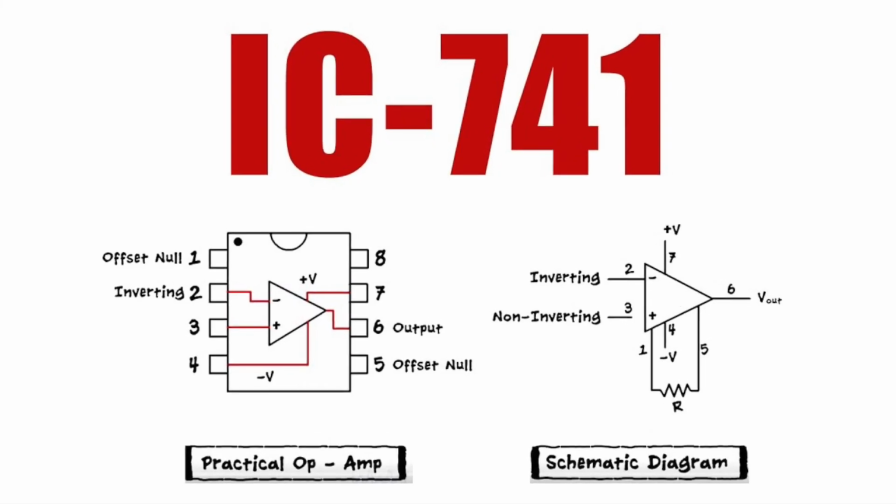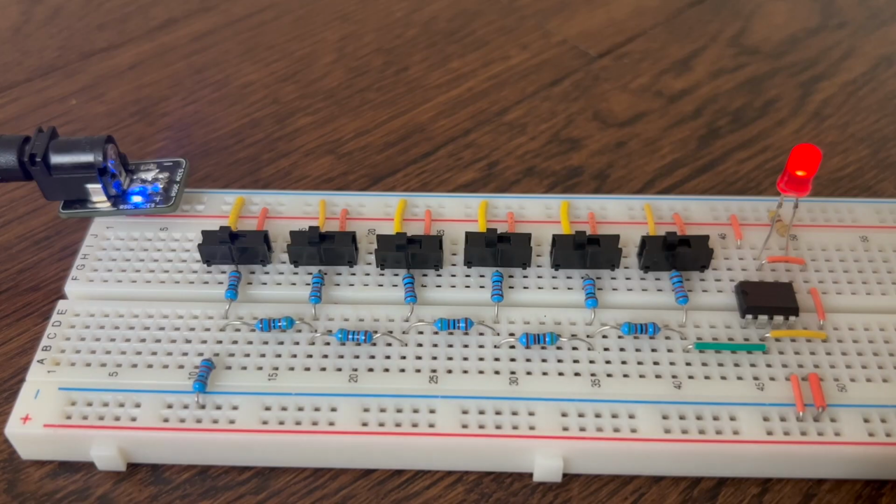The op-amp can also be used in this circuit. The two main rules of an op-amp are, number one, no current can flow in or out of the inputs, and number two, the op-amp tries to keep the inputs at the same voltage, so it has to drive a voltage in or out to keep them the same. It does this through feedback, which is this component right here. Thus, the op-amp in the circuit acts as a voltage follower, where the output voltage is the same as the input voltage.